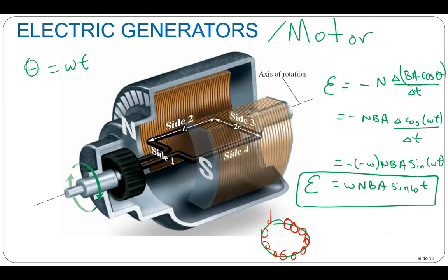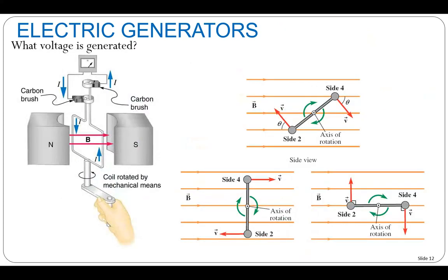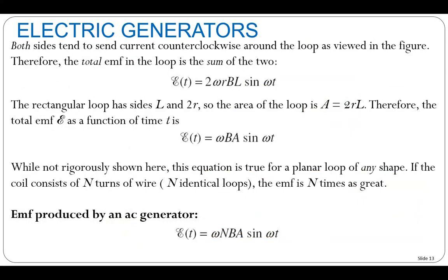Because what makes the voltage? It's the rate at which the magnetic field is changing. So if you change from north to south quicker, with just a small rotation, you'll have a larger voltage produced. The alternator is very much optimized for generating electricity, and it won't work as a motor because it's not designed like a motor. So you can't start your car with an alternator. Hence, you have a starter motor and separately an alternator in today's cars. The starter motor looks like this generator here. I'm not going to go through the picture here.